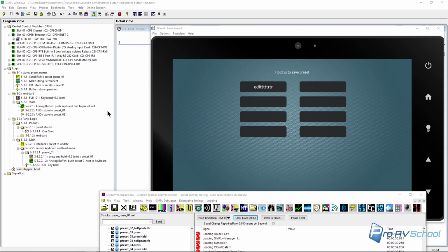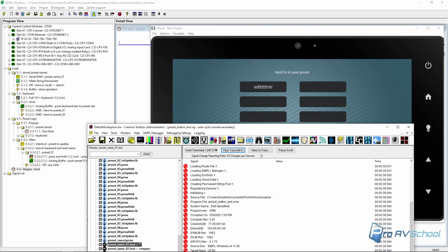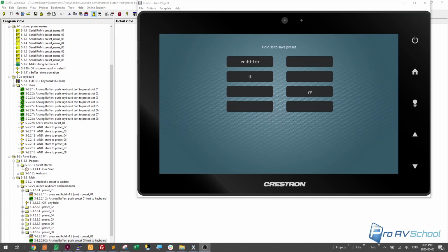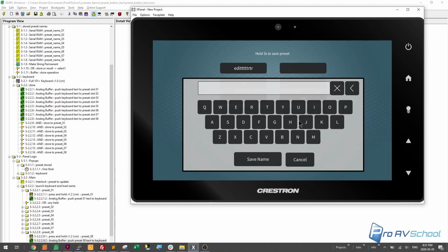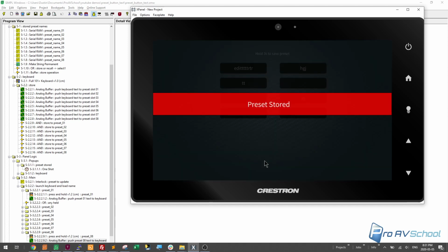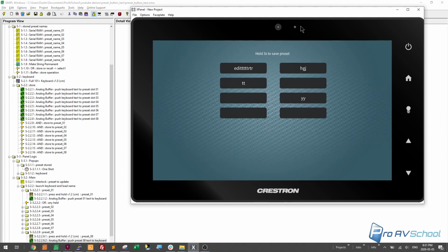So I'm just going to pause the video and go through and finish off this program, and then I'll come back and show you. Okay, so I'm back, and now I have my additional presets added to the program. The Control-Shift-V to paste an increment works pretty good if you have your signal names planned out properly. So I was able to do that fairly quickly. For you guys, it was actually no time at all. I just paused the video, but yeah.